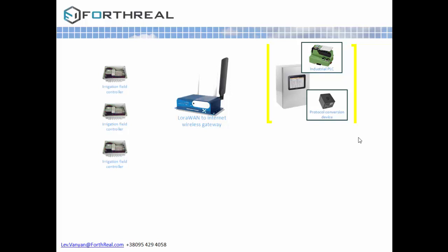The second element in the pump station control unit is the human machine interface touch panel, with the software that allows to manage the pump station manually. So whenever you need to switch from the automatic mode to the manual mode, you use the control panel and then you can switch back. This human machine interface touch panel also visualizes the current operating data of the pump station, such as the immediate electricity consumption, the current passing through the lines, and the voltages on each phase.